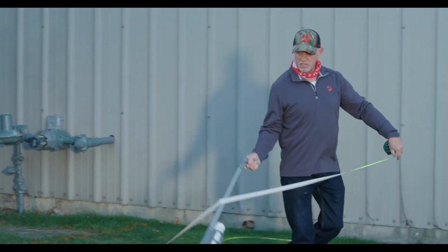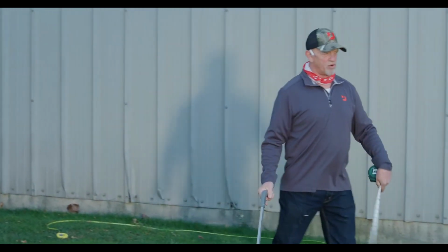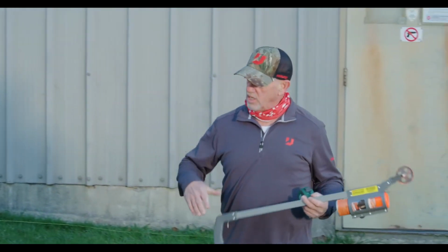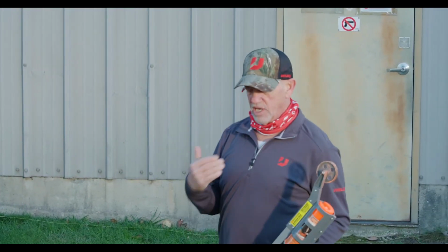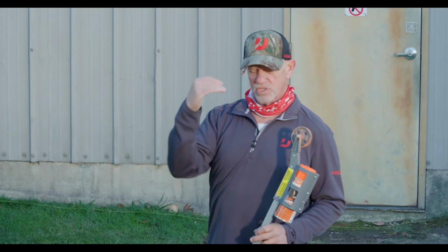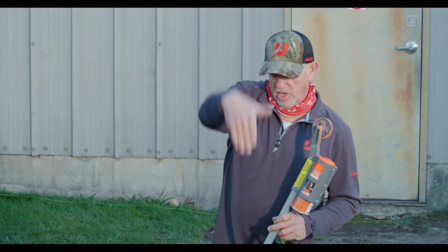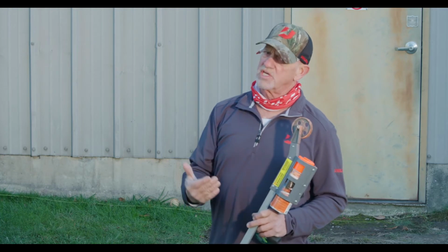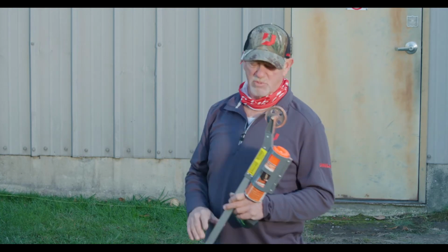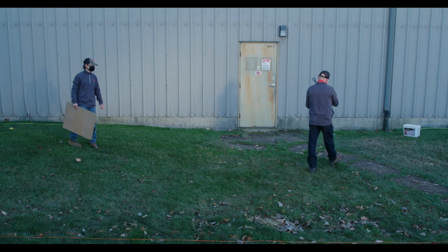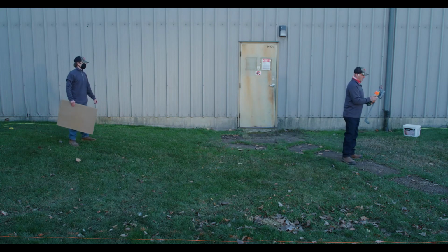Now, a couple things. I'd like to transfer over to a different color so that when the crew comes in to begin excavation, they actually see a different color that they're going to be creating that overdig area. So the overdig area that I like to use is going to be specifically 1 foot. With that being said, I'll take this paint out.